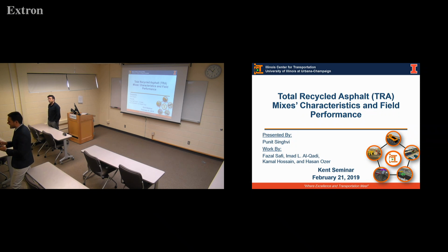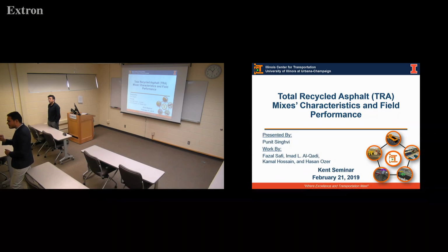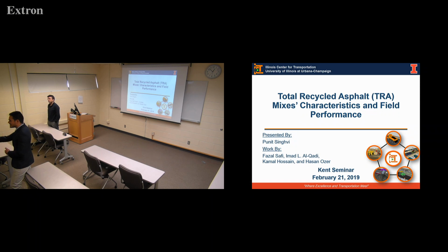Airvoids cause the crack to propagate in a more branched way. We have seen that with the fracture process zone, and also in the specimens that I tested. So when the crack propagates more branched, you will have a slope that is less steep, because the material is propagating slower. And that's what is causing the change in the flexibility index, that branching of the crack that is making it propagate slower. We saw the fracture energy changes, but not as significant as the change in the post-peak slope, which caused the change in the FI.